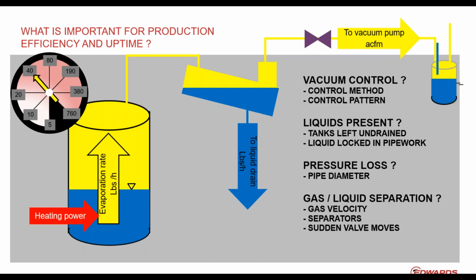But it's basically pulled down as good as it can to the position of the valve. If you open it suddenly, you eventually cause a sonic speed shock wave that goes through your system and causes liquid slugs of a magnitude that can be harmful.